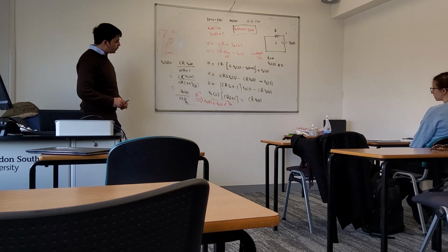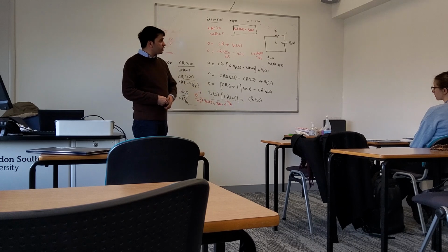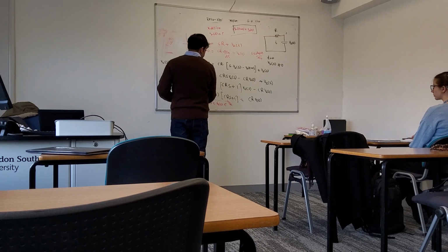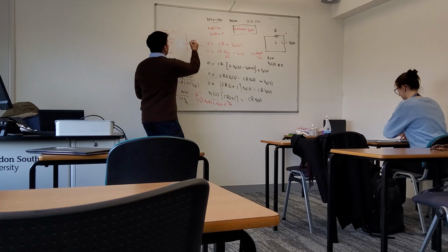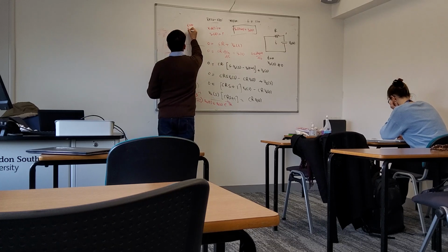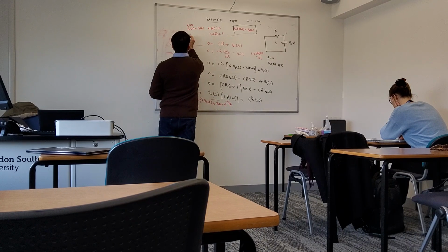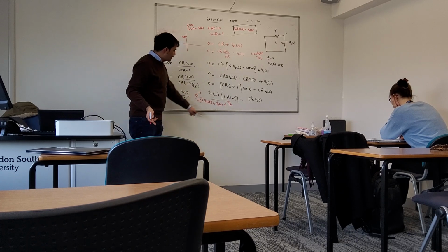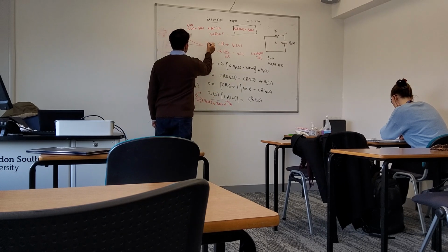So now you see there is no input in this case. If I want to plot this, to see how it looks, I can see that at time t equals 0, e power 0 is 1, right? At time t equals 0, this term would be 1, so it will start from V2 of 0. It will start from that constant point, which was the initial condition actually, right? And over time, if I put t equals infinity, this term would be 0. So it means that it will go down to a certain point.